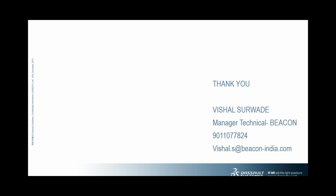Okay. It's not a single slide, it's a single sheet, it seems. Okay, it's not a single slide, it's a single sheet. That is in continuation with the previous question, whether we can place multiple views in a single slide or a single sheet. So that is a basic difference. Here we are not considering any 2D drawings. These are all 3D views, and they need to be created separately. You can't have multiple views in a single sheet as well. That you can have on 2D drawings, obviously. But in this case, you need to create each view separately.